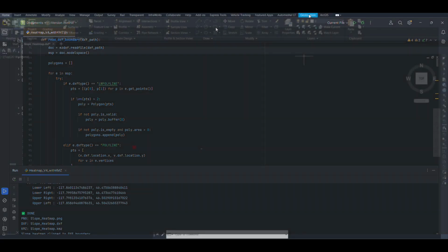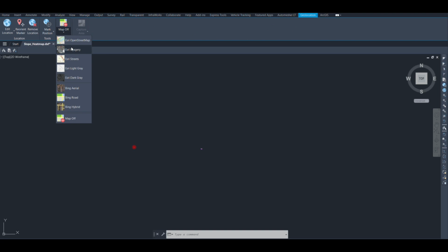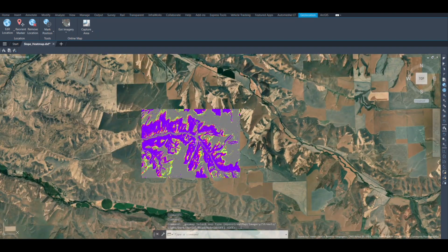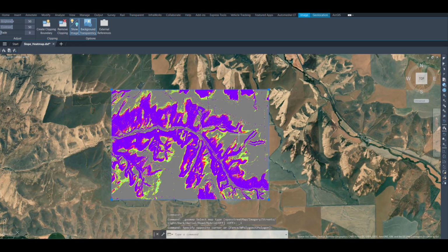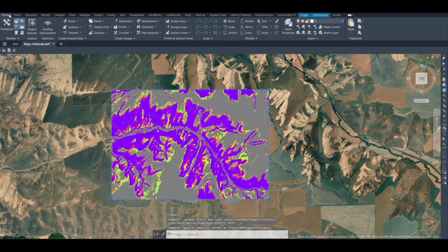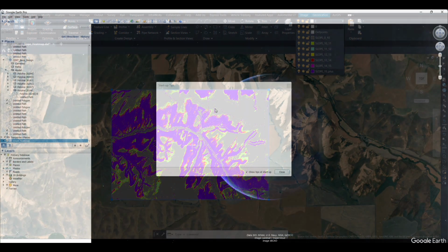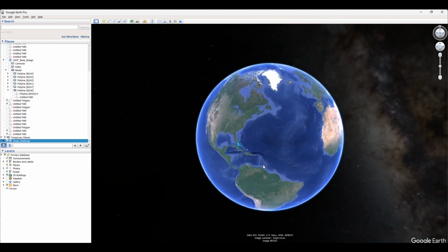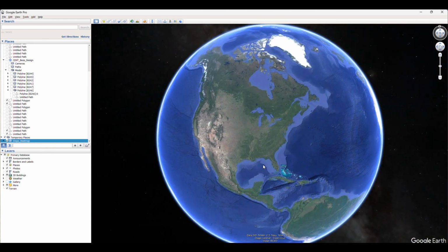After the slope classification is complete, the tool creates three main outputs. The first output is a PNG heat map. The second output is a DXF file. This DXF file can be opened in CAD software, and the heat map image is placed in the correct project coordinate location. The third output is a KMZ file. This KMZ file can be opened directly in Google Earth.